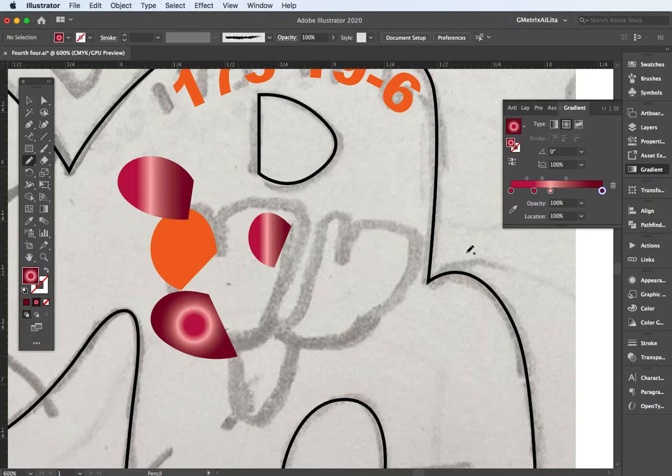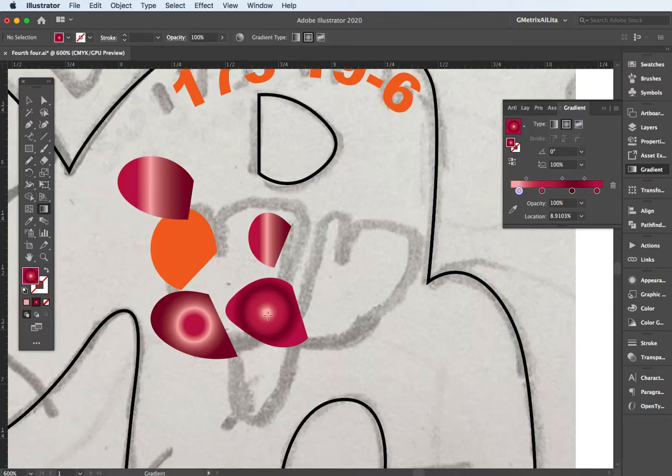It creates that piece, but if I want to have it go with a light source, I can move these on this gradient editor slider right here, putting the base tone, reflected light, and getting rid of this so the highlight is there. So now when I draw this, the highlight is in the middle. If I want to reposition this, there's a gradient tool on the toolbar, which I can click and drag, and that gives me that option.